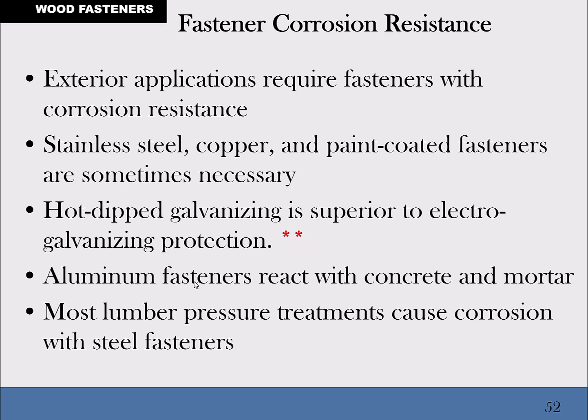Okay. Most lumber pressure treatments cause corrosion too, because they are salt-based, and so you can't just use good old-fashioned steel nails in pressure-treated lumber. You need at least galvanized coated nails, or better, or more likely a coated screw.